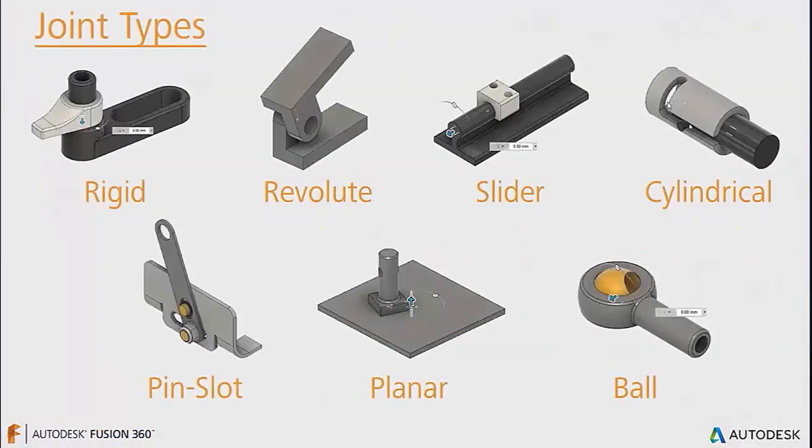Choosing the right joint type is fairly intuitive, and it's always best to choose a joint type that only opens up the necessary degrees of freedom. This will keep the model from moving unexpectedly. Not only will this make the model more robust, but it will also reduce the computations needed when experimenting with the assembly, which will help speed up the design process.